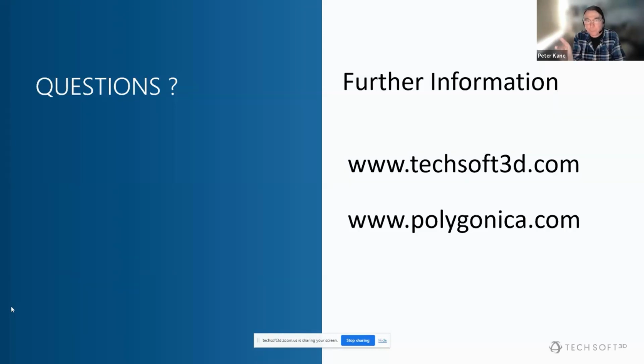It depends how deep you want to get into Exchange programming, but essentially, earlier on I showed we've got these representation items that a part definition can represent, and you could, in theory, take the mesh that you've taken from Polygonica and replace the representation item that represented that in Exchange. I think if you were only interested in the individual part, it won't be too bad.